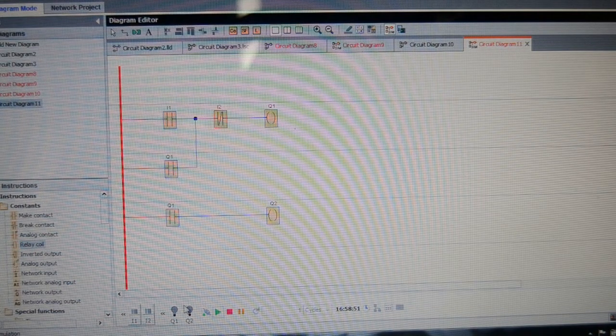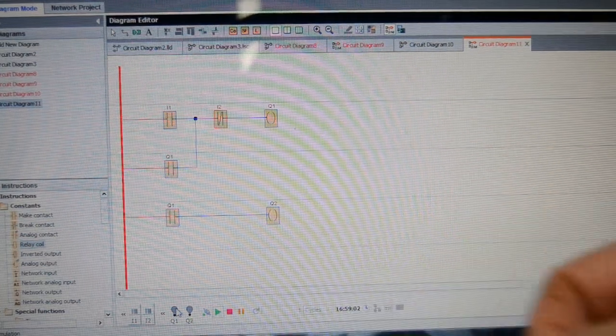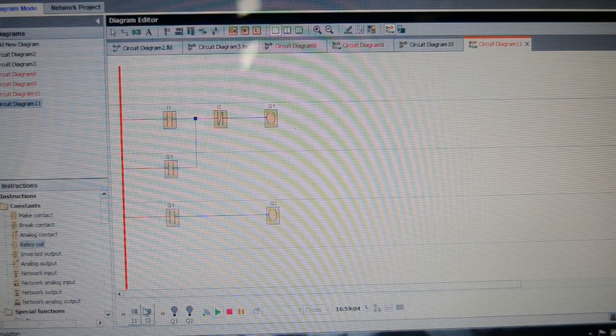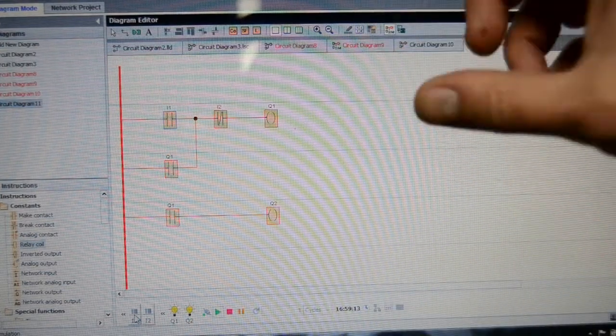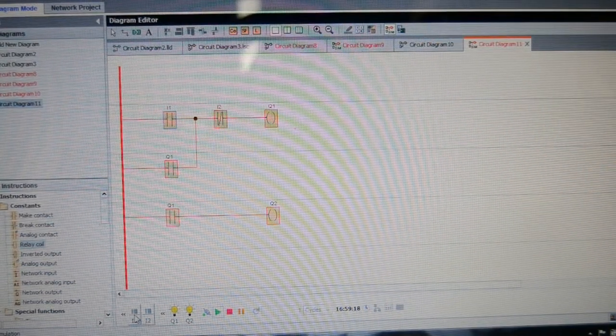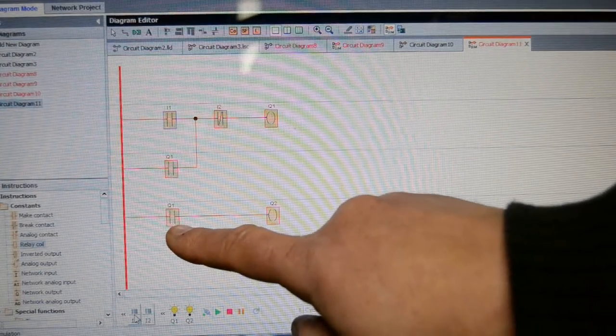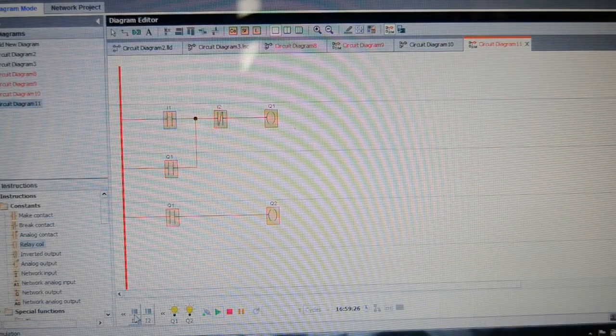Now we've got two lights here. Remember, Q1 may not actually be a physical external light. That's just telling us that that coil is switching on. But Q2, we can imagine, is our motor. So when we turn on the input, as you see, both lights come on. So Q1, which can be entirely imaginary, just digital held within the PLC contactor, is closing this imaginary PLC contact here, which is turning on this external light, which is our motor drive, our production line, our conveyor belt, doesn't matter.